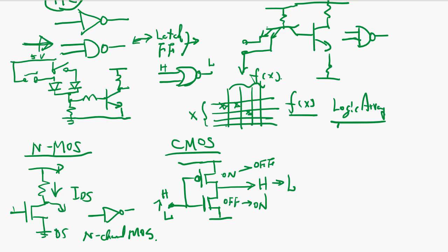So basically you have a turned-on transistor at the bottom and a turned-off transistor at the top. So this on and off timing has to be adjusted very precisely by setting the threshold voltage condition for this CMOS. Otherwise, if you turn this off first and you turn on the other MOS device later, there is some transient problem.